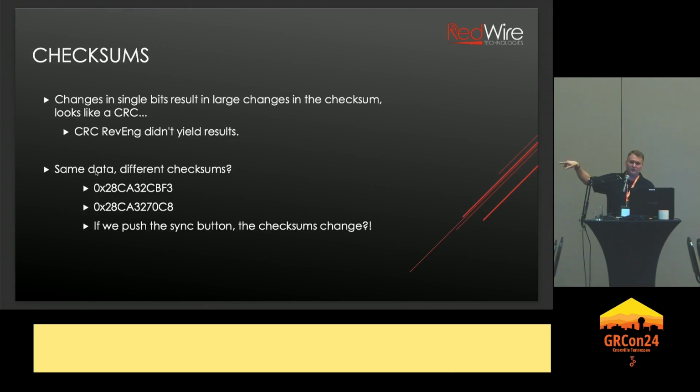But those 2 different checksums come from when you press the resync button on the thermometer. Every time you push it, you'll get that 7 I mentioned for a resync message, and that checksum will be different from that point forward, even for the same data.